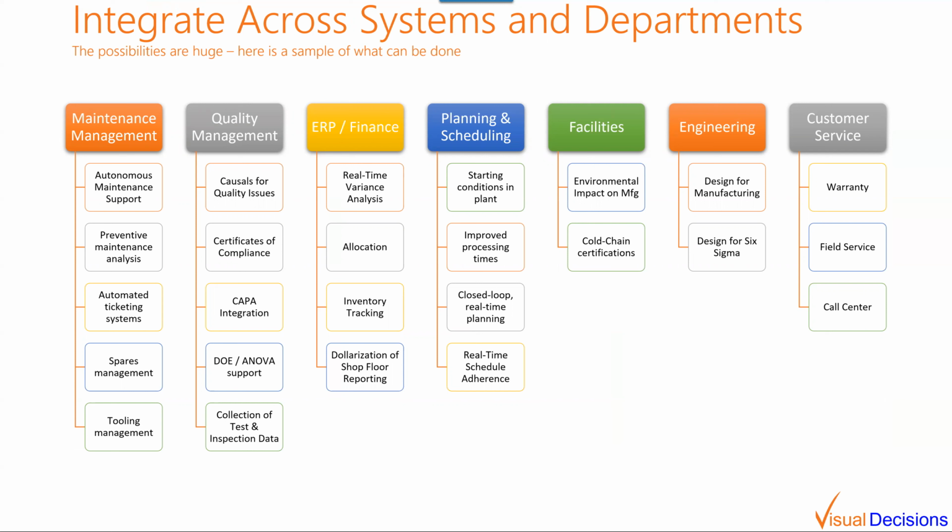So for example, connecting the information from the machines to the maintenance management system enables a lot of additional capabilities within manufacturing. One example is to present autonomous maintenance checklists to the operator each morning, or whenever the task would be due. And this works best when it's a common process, no matter who's working at which machine on any given day. By including work instructions for the tasks, it can greatly simplify job rotations and having people step in for absent workers.